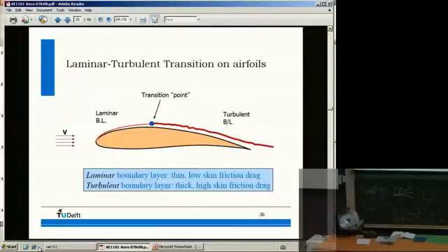On a similar concept, of course, flow around an airfoil or wing: laminar flow, transition point, turbulent flow. And it depends on the conditions. Your transition point can be anywhere. For gliders, so for really low speed aircraft, they design for as low friction drag as possible. So to have laminar flow, and they manage to have laminar flow up to 95% of the wing.